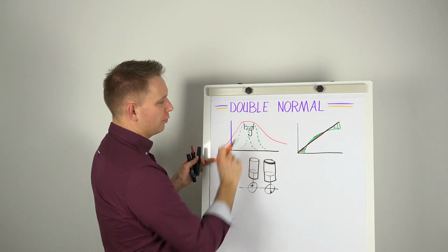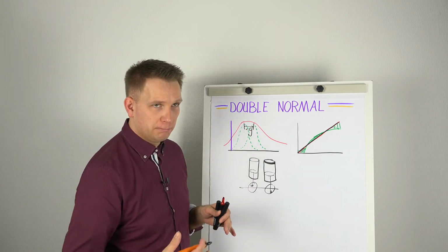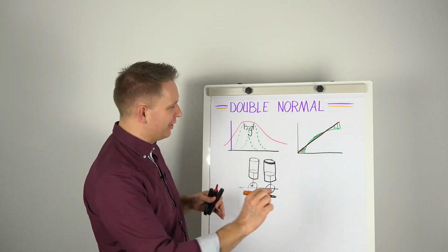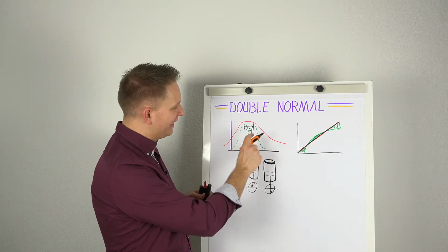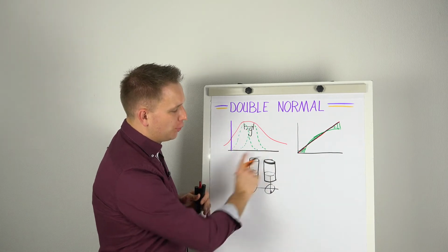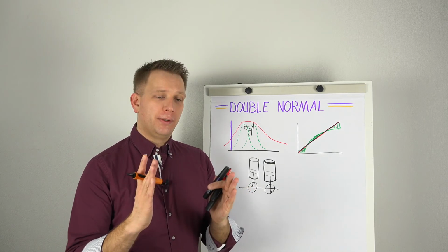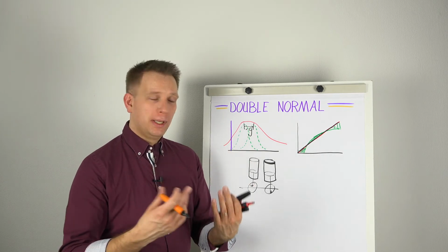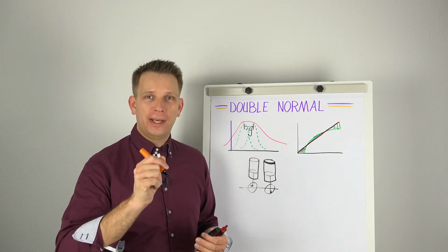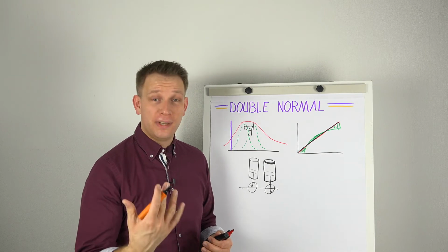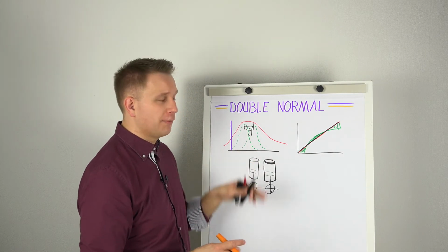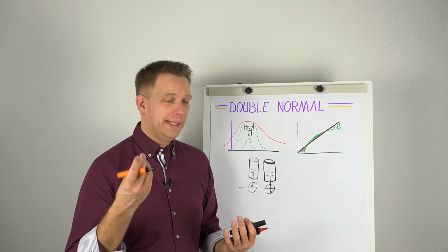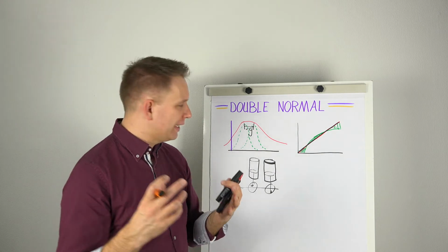that it is so many grams or pounds or liquid pounds or whatever, but let's keep our engineering in the metric units. So many grams. And what does it do with our physical system? Do we need to reduce the cylinder size, do something with how it is pumped? Is it perhaps the servo that is a bit too slow opening a valve? Because that is also very possible. The valves that are on top that open or close the product flow, maybe one of them, the spring is not good. So these are the typical things to check.